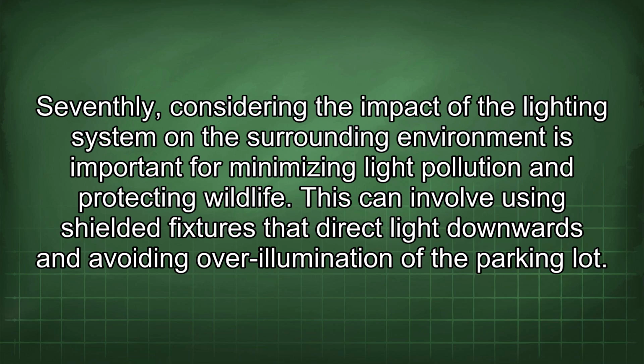Seventhly, considering the impact of the lighting system on the surrounding environment is important for minimizing light pollution and protecting wildlife. This can involve using shielded fixtures that direct light downwards and avoiding over-illumination of the parking lot.